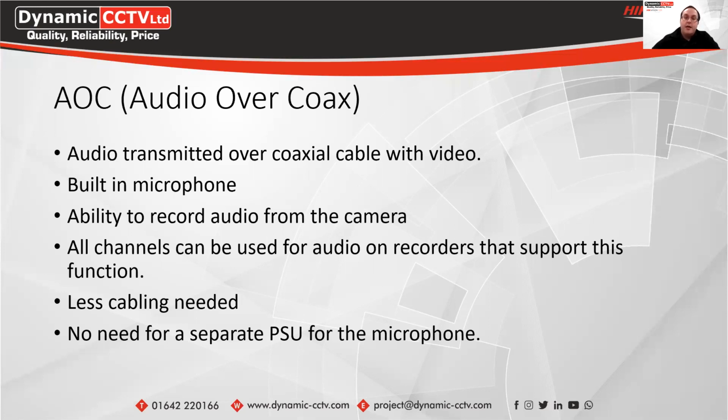Hikvision have brought out the new TVI recorders which have audio built in, and there's also the new IDS Accusense units which actually combine the AoC technology as well as the Accusense alarm filtering. So this allows you to have a single coaxial cable or Cat5 with balun, and you can actually have a built-in microphone in the camera, and that audio would be transmitted down the coaxial cable with the video signal. These do need a power supply for the cameras, so it's not AoC with PoC.